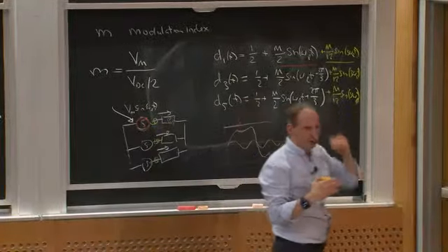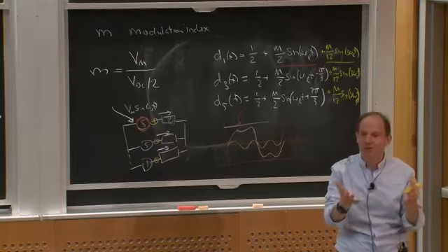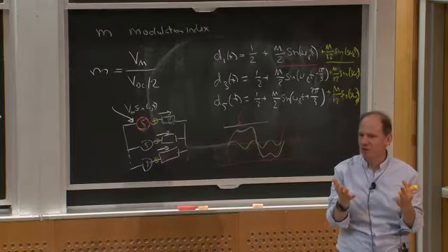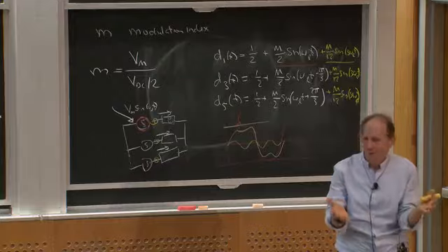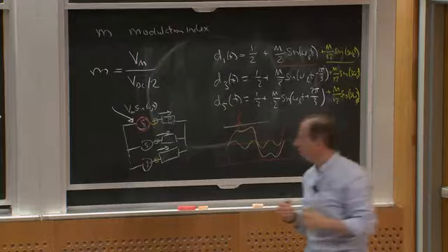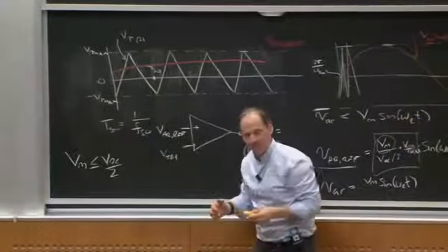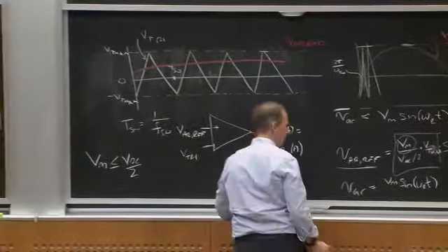That gives me a little bit more headroom to synthesize a little bit more voltage, and we're often constrained by how much voltage we can synthesize with our inverter. What do I do if I'm not happy about that? Well, I could just keep turning up M beyond 1. What happens if I turn up M beyond 1?